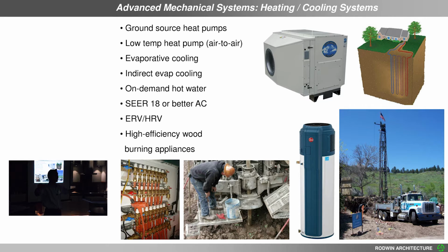But with an ERV, if you seal up the house tight, then you have to ventilate it right. What that means is you have this device that tempers the air as it comes into the house. It's almost like there's a radiator grill where air that is conditioned to 70 degrees inside the house is passing along this plate. Let's say you were sucking in 10-degree air on a cold winter night from outside. It exchanges the therms from the warm air through this plate into the air that's coming into the house. So it tempers the air and can dramatically reduce the energy loss from bringing in fresh air into the house. Because you do have to mechanically introduce fresh air into the house so that you don't have sick building syndrome or just a stuffy house.